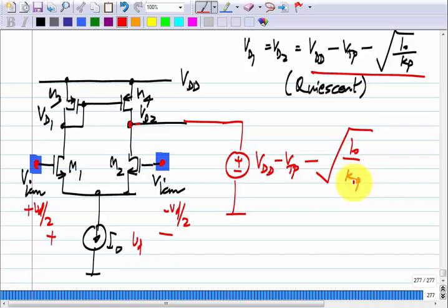Is this fine? How much current will be flowing here? Yeah, 0. Why? Voltage, yeah. If you did not connect anything, this voltage anyway would have been that, and you connect it that way, no current will flow. So, this will not disturb the bias point anywhere. That is the idea.